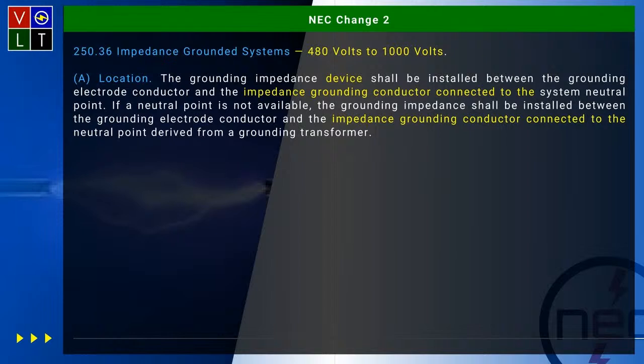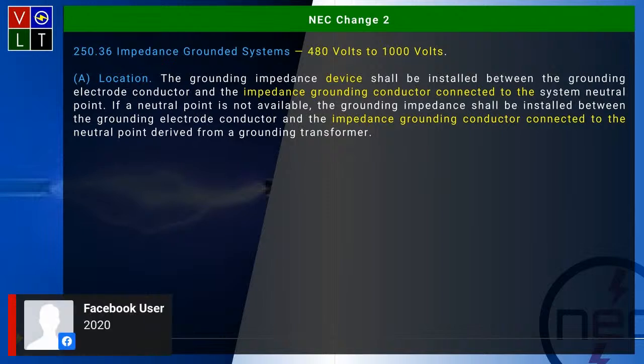When you get into that, you're looking over at 314.16(B)(5). And basically it says for 4 or less, you don't have to worry about counting. Once you get over that, based on the number of extra equipment grounds in there, you have to take that at a quarter, which will be 0.25, and that will cover that.